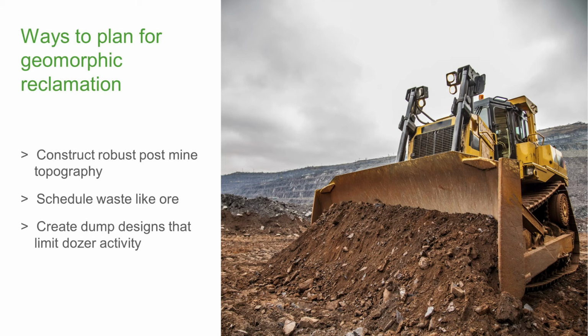So, ways that you can plan for geomorphic reclamation. One item is you can construct a robust post-mine topography. In the United States, a post-mine topography is a requirement for an annual permit, and that is corresponding to the operator designing a surface that best reflects what they anticipate their topography to look like after they cease operations. This is a good starting point to identify how you want your topography to behave and look once you've completed